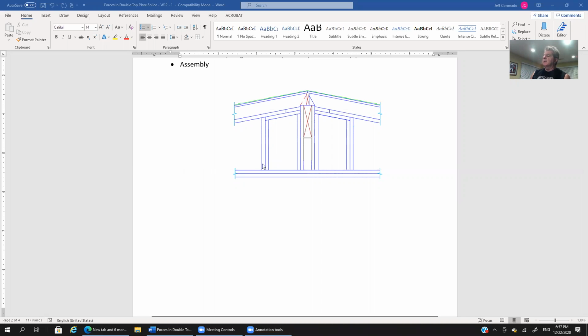You know, again, in this case, the double top plate is so far away, several feet, and separated by studs or cripple studs, that the reality is that chord forces aren't going to migrate all the way from here where they're generated in the sheathing down to that double top plate. So we need to find something that's in closer proximity. And in this case, we found it with this rim element.